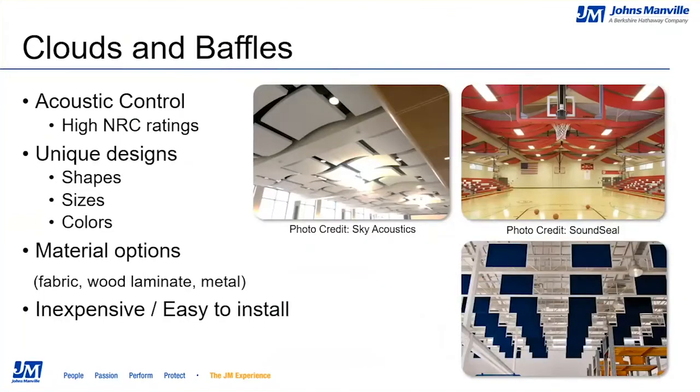If the office design doesn't include ceiling tiles, baffles and clouds are another excellent choice to control noise. These products have similar benefits to acoustical wall panels, but can be utilized throughout an office space. The unique designs, shapes, sizes, and colors available offer an infinite amount of creative choices. Many of the cloud and baffle designs include factory-installed attachment hangers, which make them easy to install with adjustable hanger wires. The spacing of the baffles should be considered if optimal acoustical control is desired.